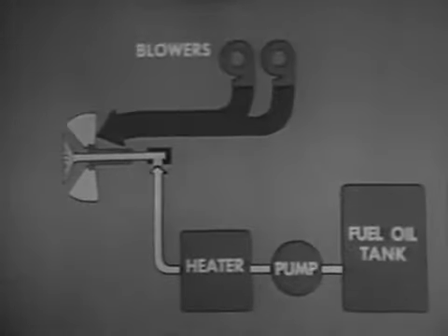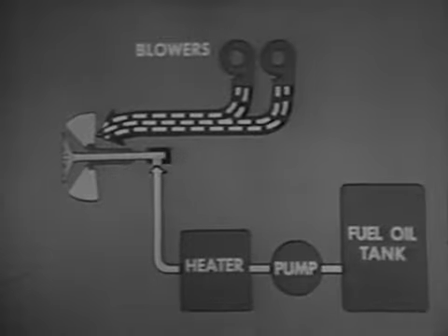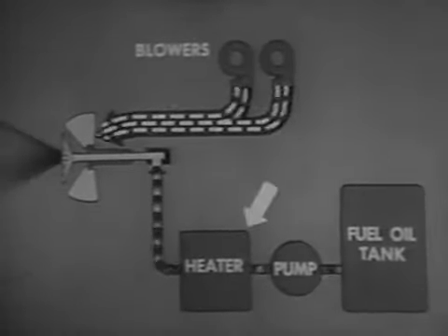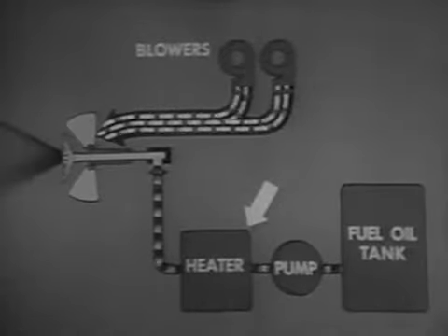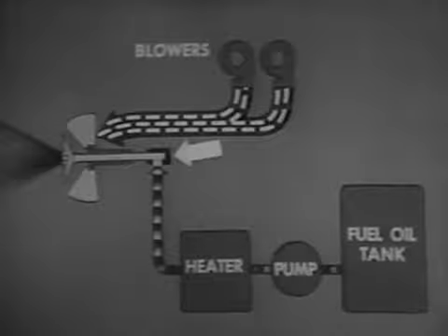The forced draft blowers send a strong blast of air to the burner. The fuel oil pump sends the oil through the heater, where the oil is heated to give it good flow qualities. Then the oil is pumped to the burner.